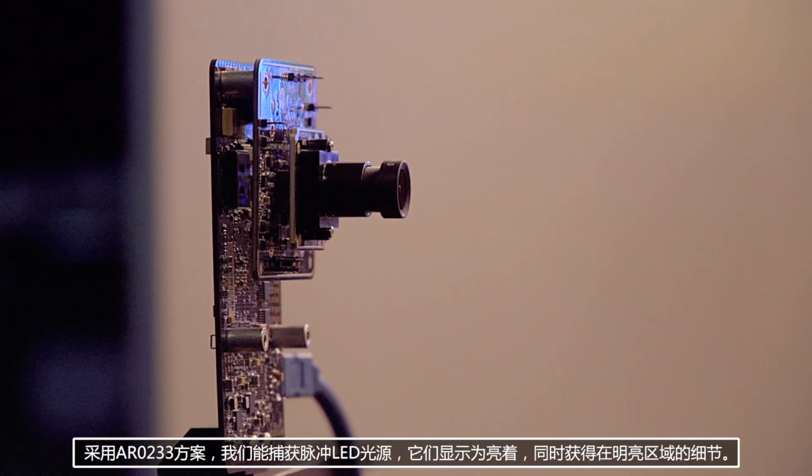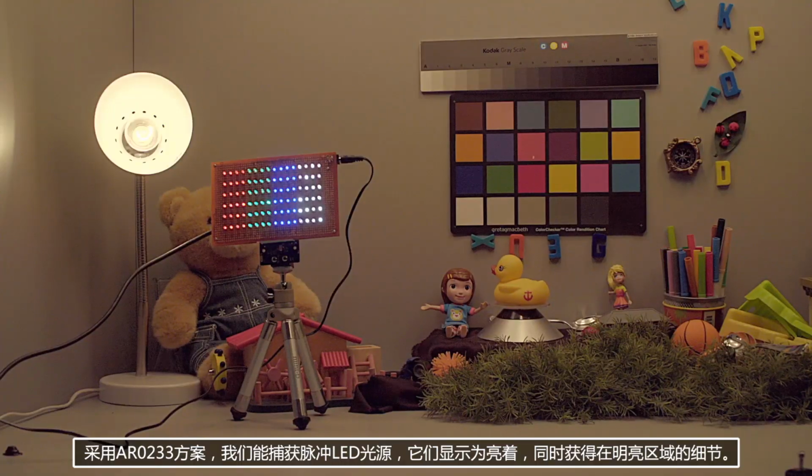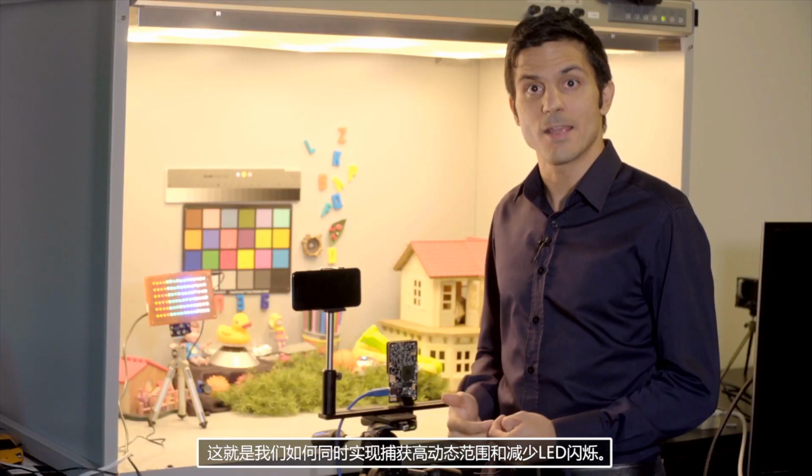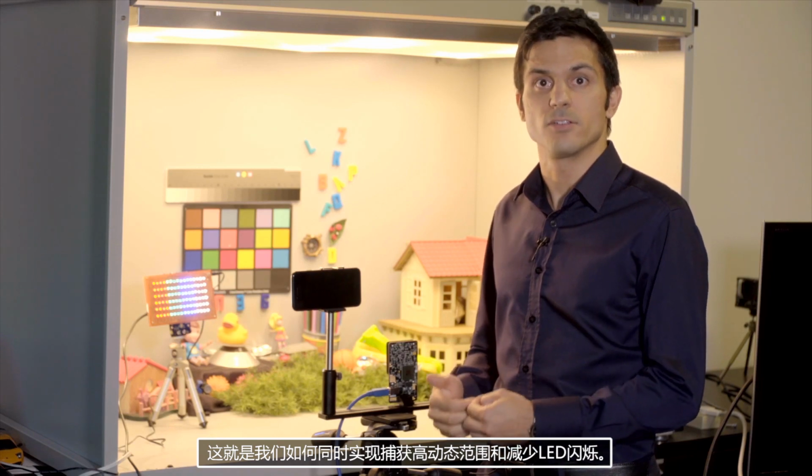With the AR0233 solution, we're able to capture the pulsed LED light sources and they show as being on, while at the same time getting the detail in the bright areas. That's how we enable simultaneous high dynamic range plus LED flicker mitigation.